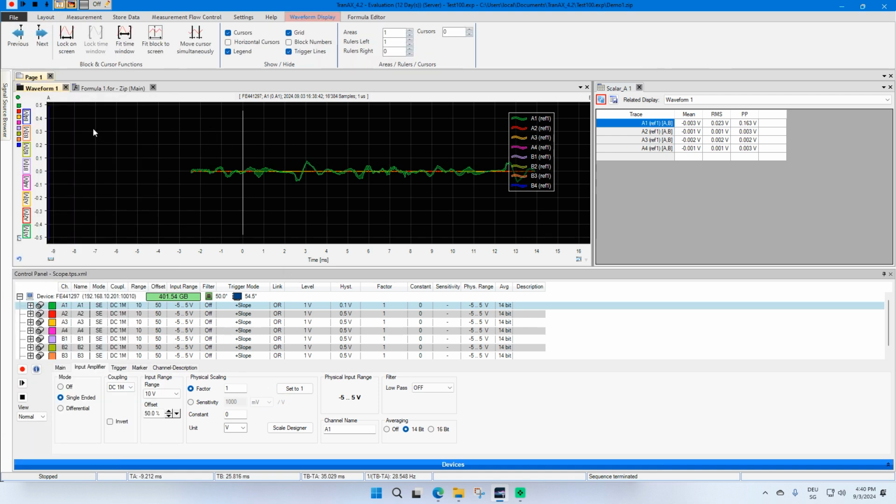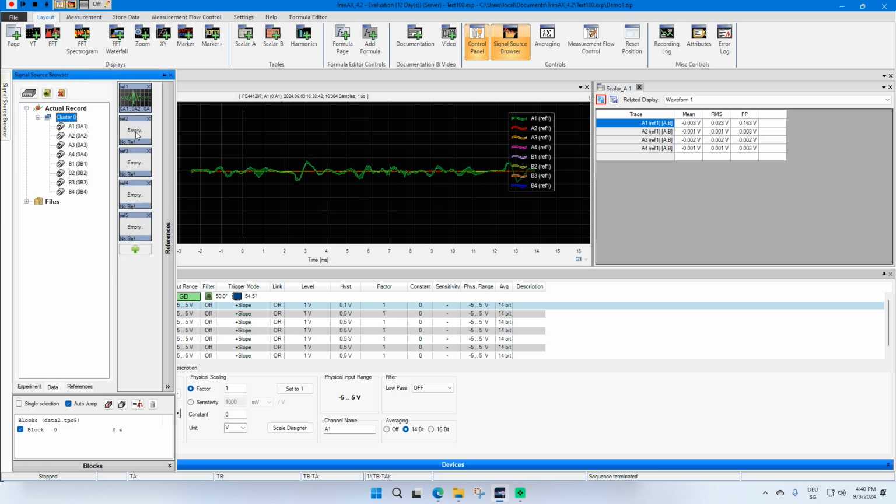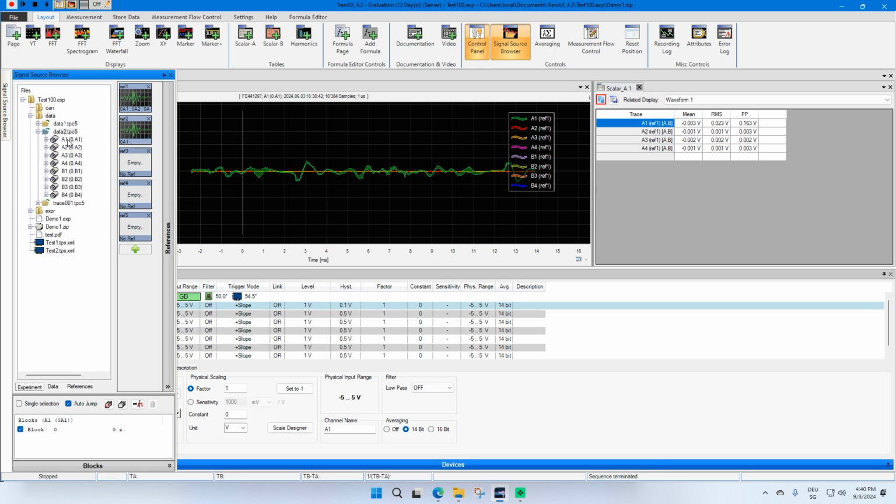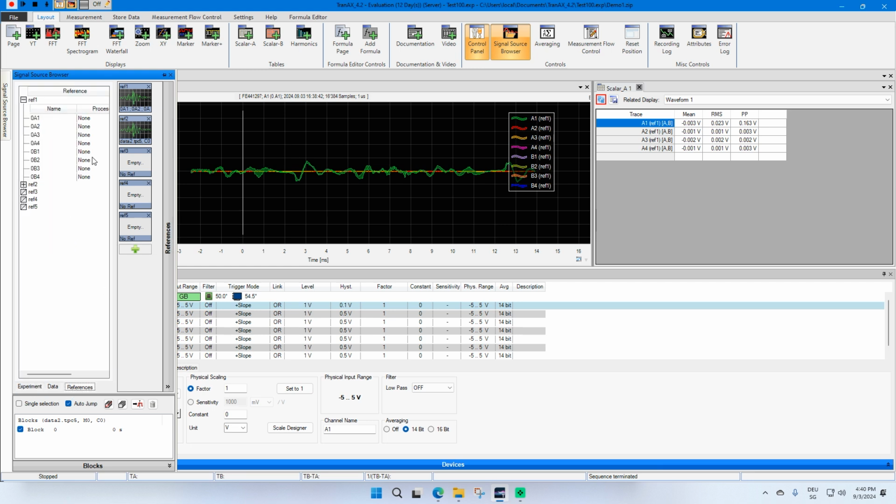You can also configure a reference with only one channel inside. So you can say, okay, reference 2 is only channel 1. That's also possible, but then you have also to change from only one channel here. So if you want to replace a file with several channels, it's easier to have all the channels in one reference. To have a look what is inside your reference, you can go here in the reference tab and you see my reference 1 has 8 channels here and reference 2 has only 1 channel here.